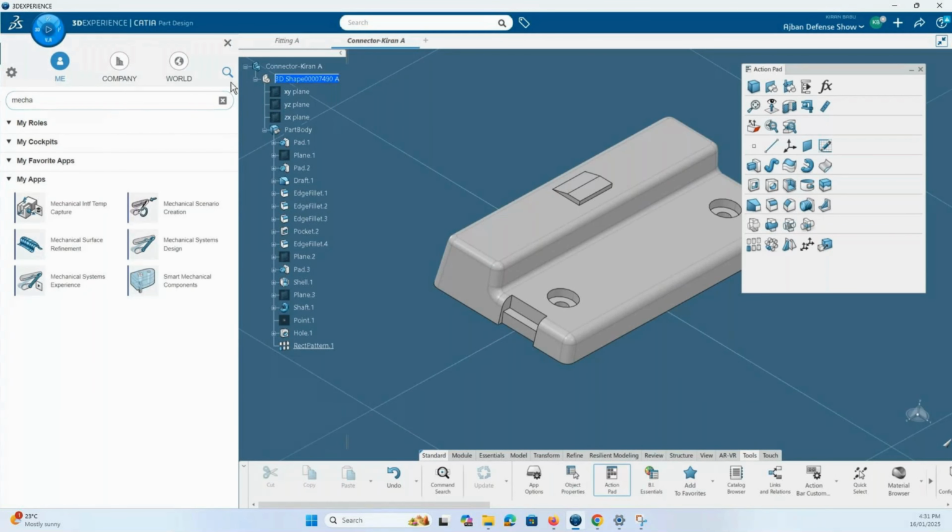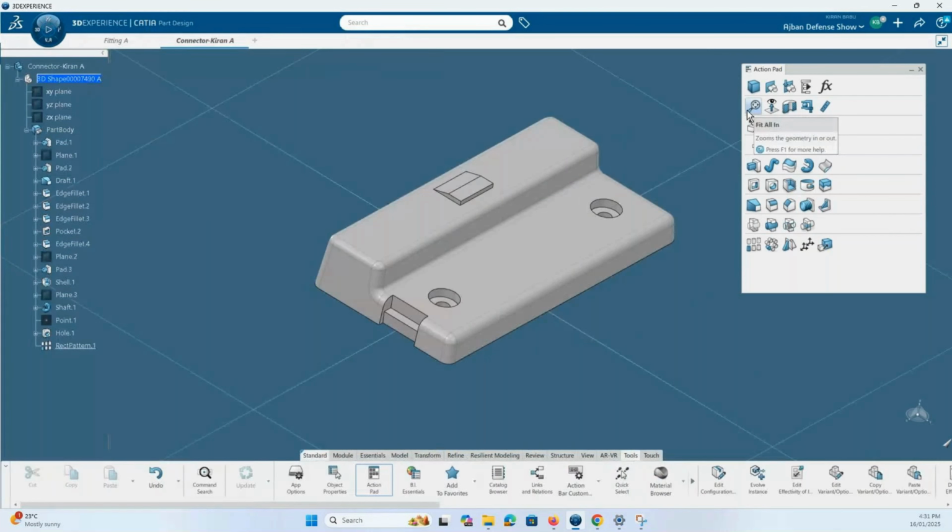If you have files not just in CATIA but also in SolidWorks, whether it's .SLDPRT or .SLDDRW, or if you are from the CATIA V5 space, .CATPart, .CATProduct, or any kind of drawings, in order to import those particular files, you can click on this plus symbol here, go to Import. You have a small arrow here.